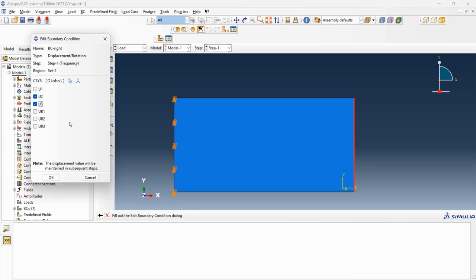If you really want to know the crucial factors that boundary conditions play in the modal analysis, you can ask me in the comments. Maybe I will do another video to go into detail about that, or just answer if it's short. It's going to depend. But right now, you just need to know this: you don't block along X, because this is the longer length. It's along X, so you just block the other axes.